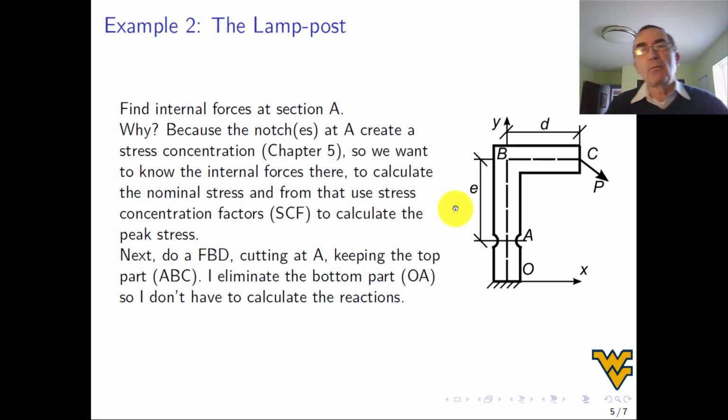Why do we want to calculate internal forces at some section? This question always comes up. Well, we have to calculate internal forces because we want to calculate stress to compare with strength to see if the part will fail. So if we see a section that is notched, like this one, you see it has these notches here, then there is a reduction of cross-sectional area, and also there is a stress concentration, which are all topics that we will cover in this class later. And so we know that the stress is going to be higher there.